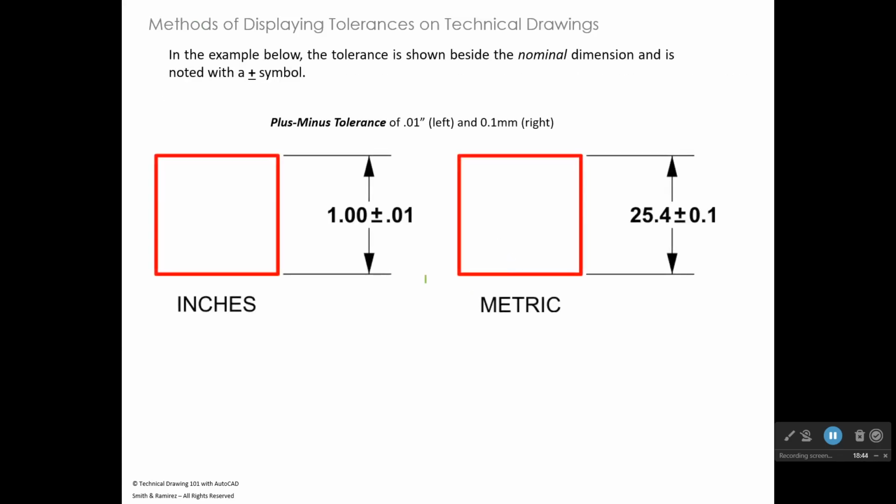Let me see. Here's an example of a tolerance on a part. So if you dimension this part and you said that from this plane here to this plane here, when that's measured, as long as it falls between 1 inch plus or minus 1/100th of an inch, that feature right there would pass inspection. So when this part is inspected, they would measure the distance from the top plane to the bottom plane. And there's some really sophisticated measurement instruments out there now, or you could even use a micrometer or a caliper, which is a handheld thing. And even those have become digital, so they're very accurate.